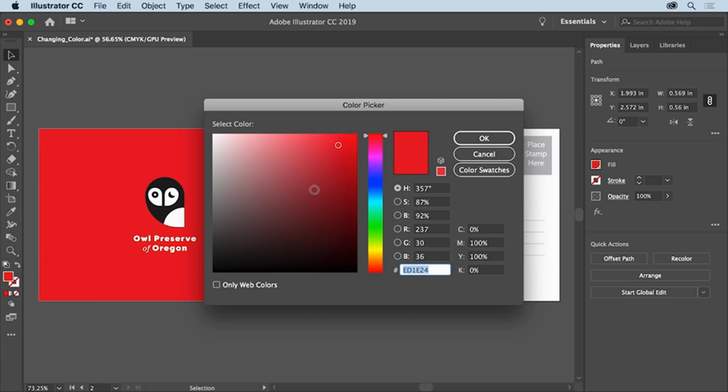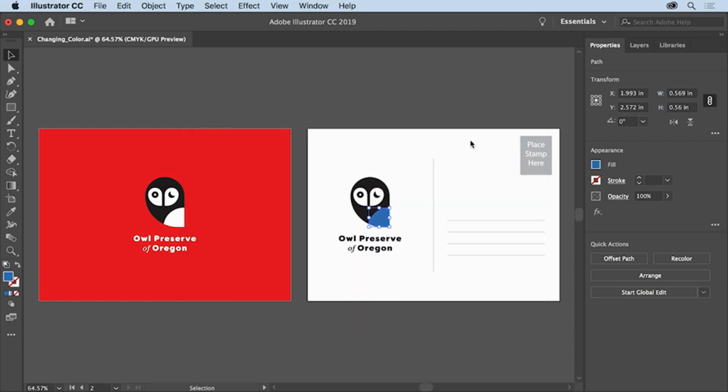Now in the color picker dialog box, you can create color in a lot of ways. Visually, typing in exact number values, even choosing from existing color libraries that come with Illustrator. You'll create a color visually. If you drag in the color spectrum bar here, you can pick a color like a light blue color. To pick the exact color you want, you can then come into this color field and click. The color you selected is showing here. Now to apply the color to the fill of the selected shape, simply click OK.